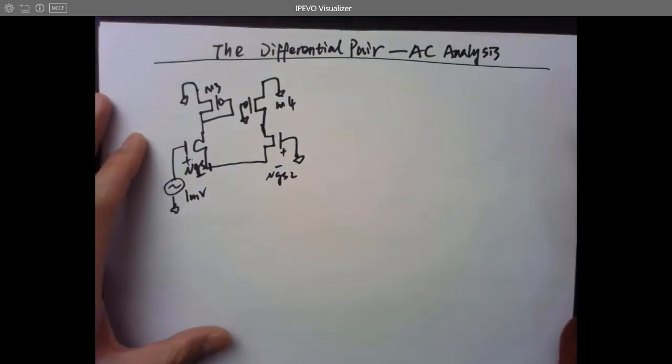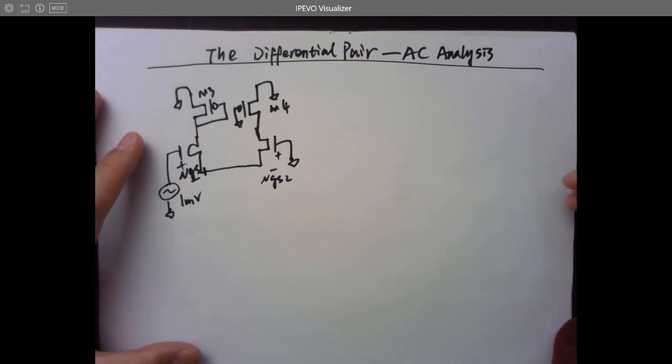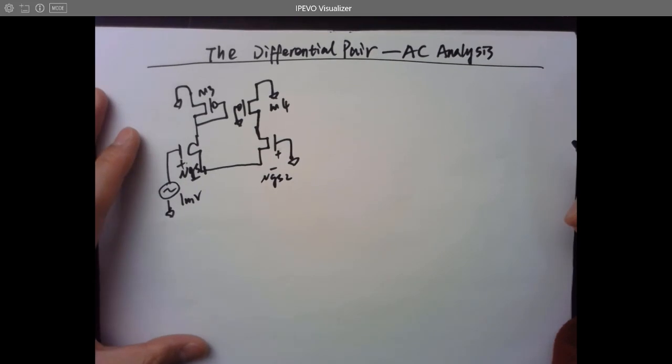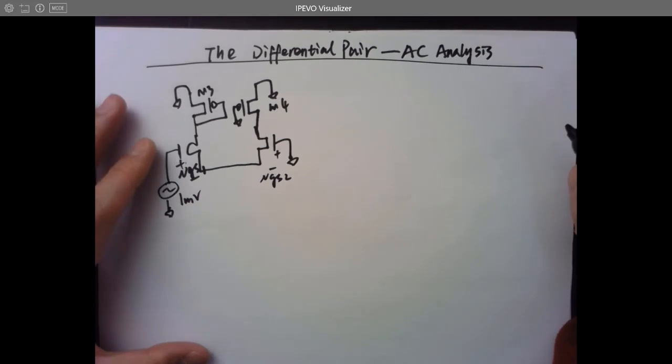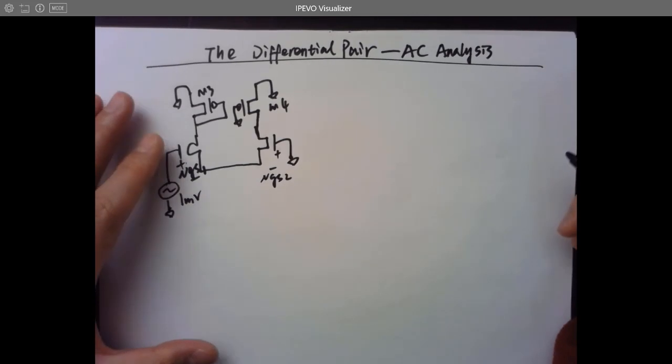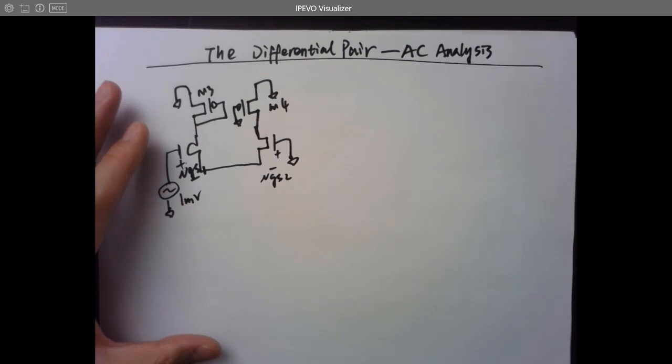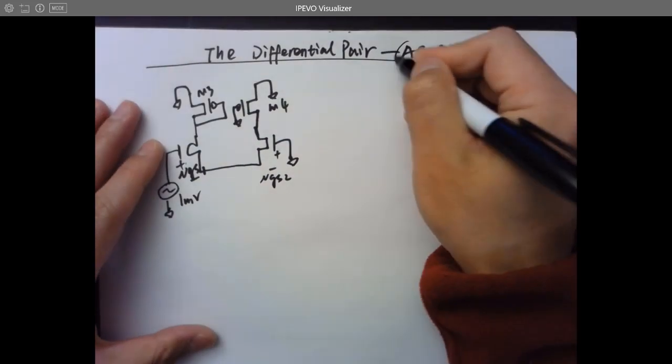It's the same theory, same rules as when you are doing a Thevenin equivalent circuit. You short the DC source and disconnect the AC source. AC analysis actually is the final purpose.